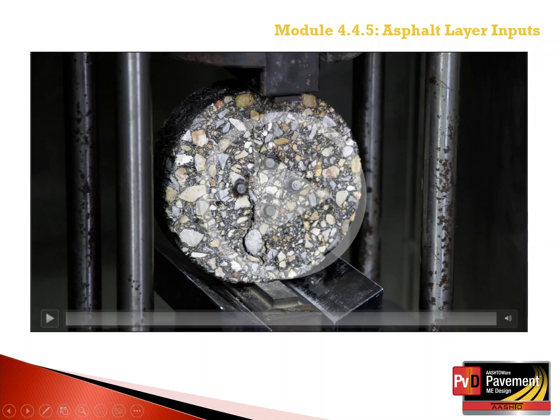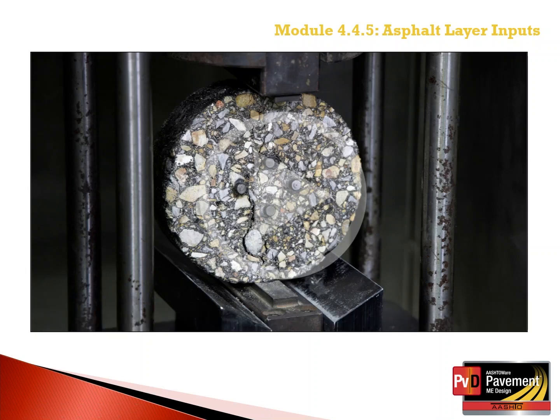So it was observed that a crack occurred and goes around the larger aggregate particles because it's at a higher test temperature. In indirect tensile strengths measured at the colder test temperature, the cracks sometimes go through the larger aggregate particles, again depending on the aggregate type and adhesion between the asphalt and aggregate.